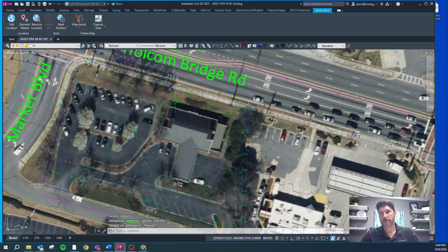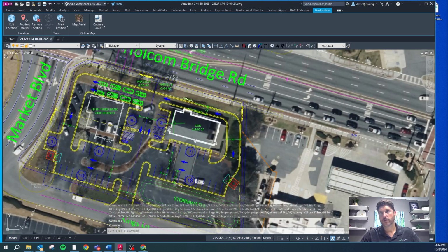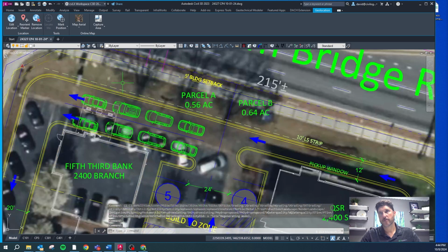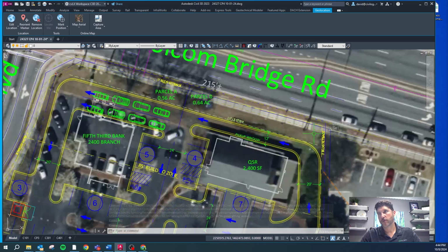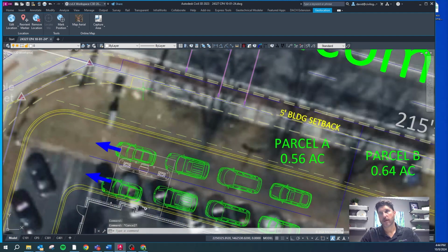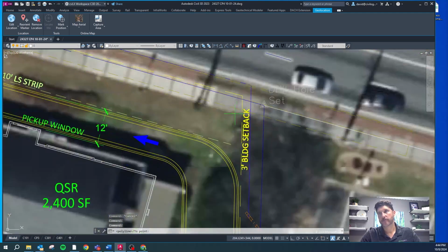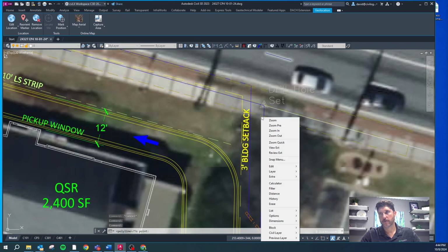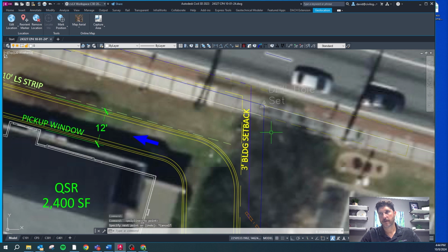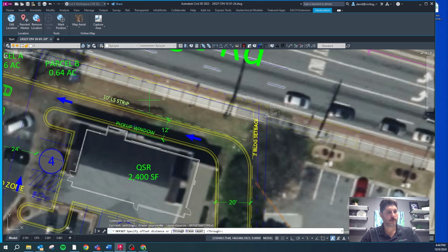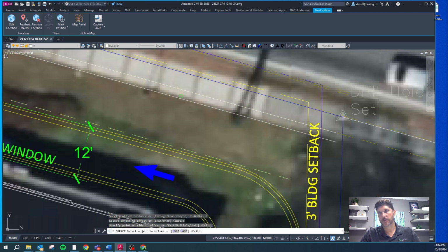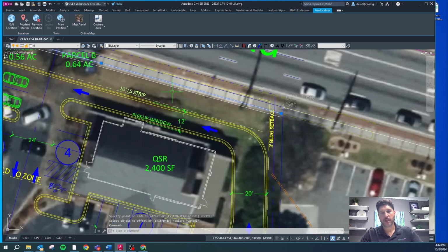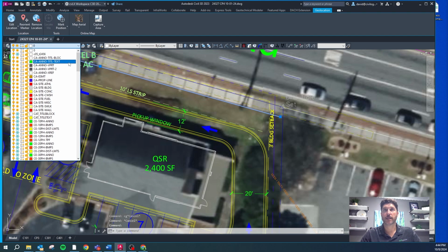And then going back to the site plan. One of the things that was important before, I know that the city of Roswell likes to make you dedicate space behind the sidewalk. We're going to come off, they usually want 1 foot, but I don't think that sidewalk's in the right place, so I'm going to do 2 feet, and we'll pretend like this is going to be the new right-of-way dedication.